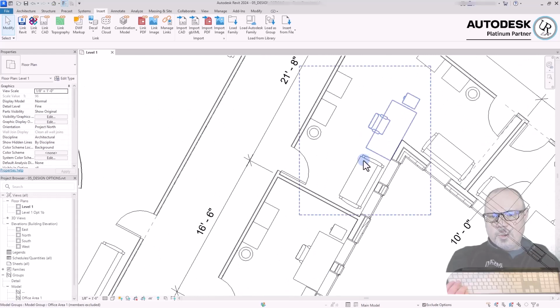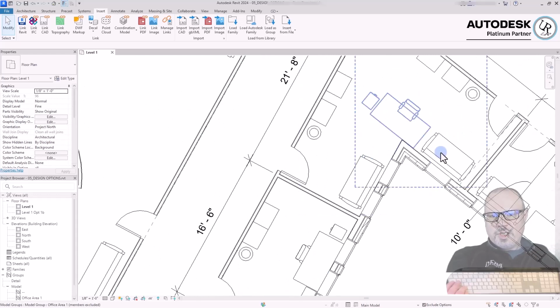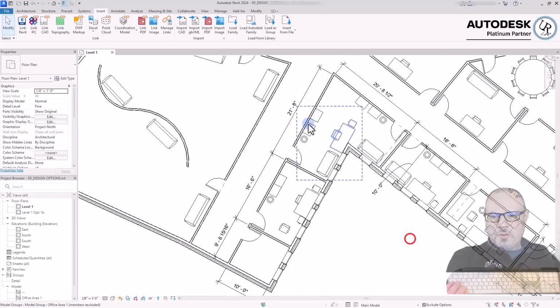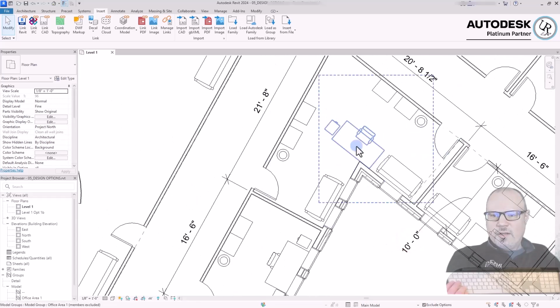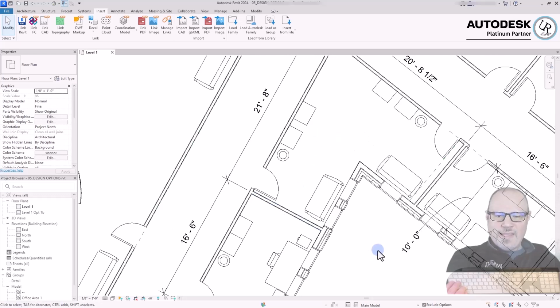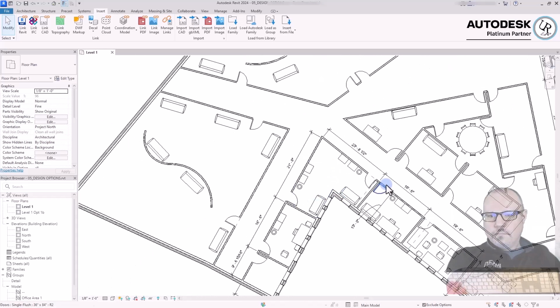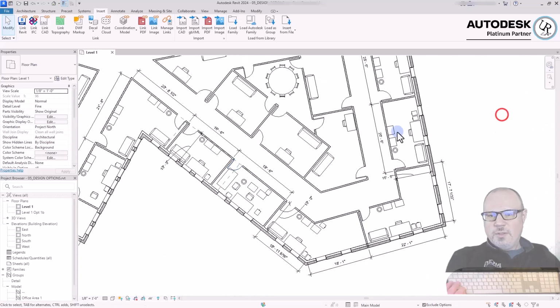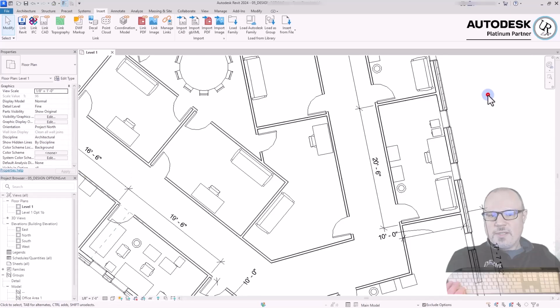As you select the group, those hidden elements will still show up, and if you make modifications to the group, they will still adjust that group as well. That object is just turned off in that group location and will not be included in counts for the furniture or for components, so they will not show up in the schedule and can be counted appropriately if you are excluding those from that space. You can have as many groups into the project as you want with as many different group types, and each one can be utilized over and over again from the properties drop-down list.